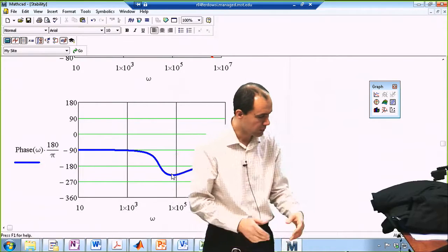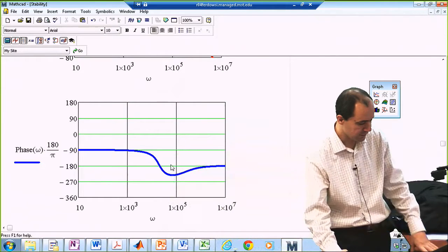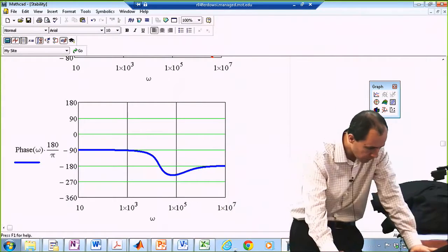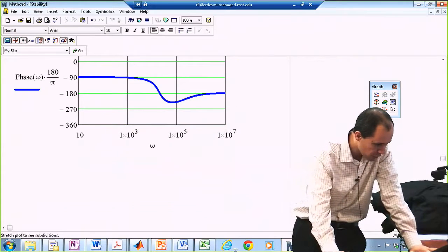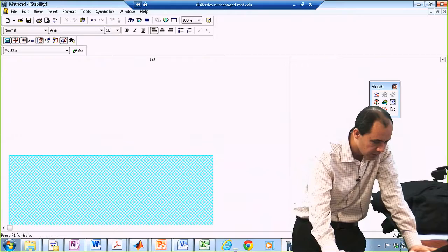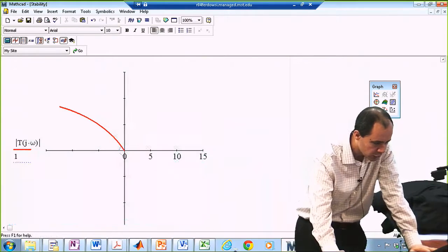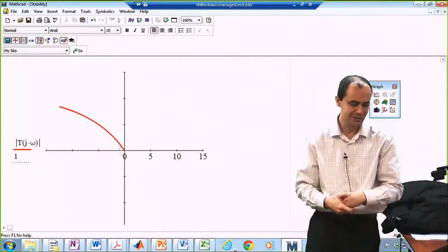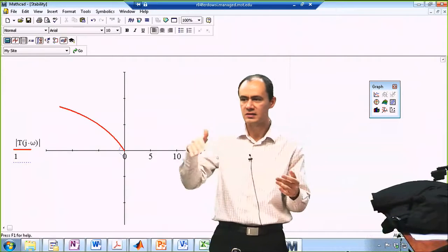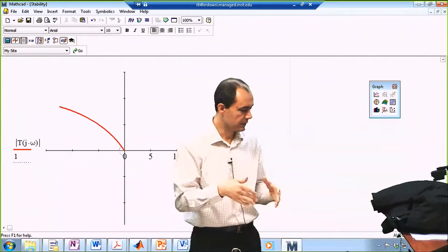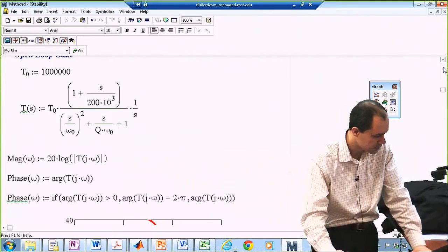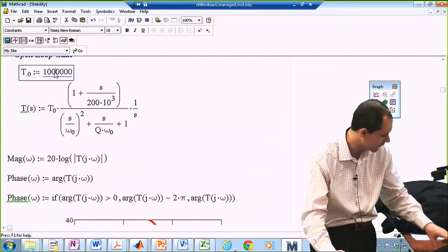Oh, by the way, there are better ways of evaluating the stability of a system than these Bode plots. The most comprehensive one is the Nyquist theorem, especially when your transfer function is weird in the sense that you cross the gain of 1 several times. I'm not going to explain it, but it's another graphical way of doing that.